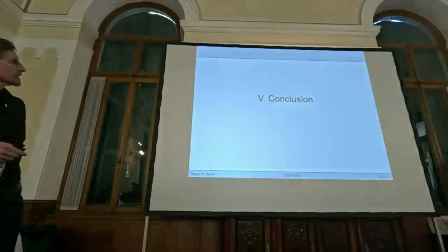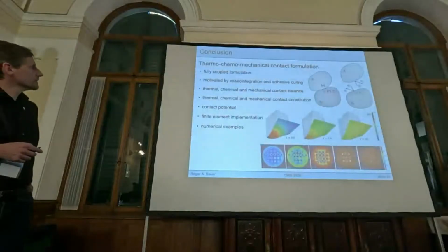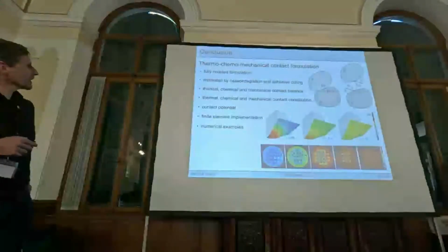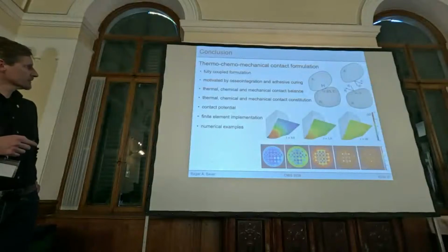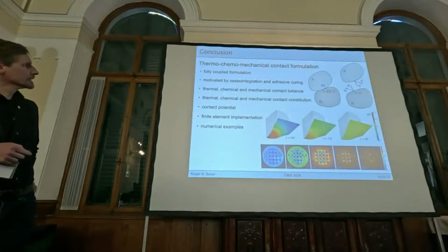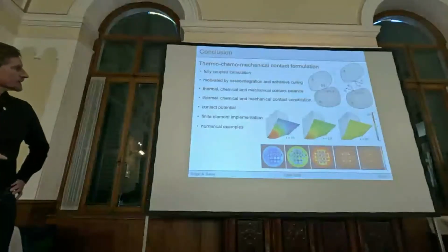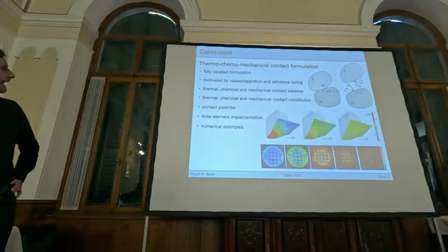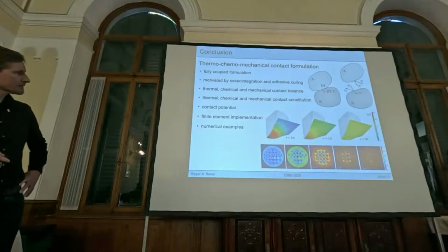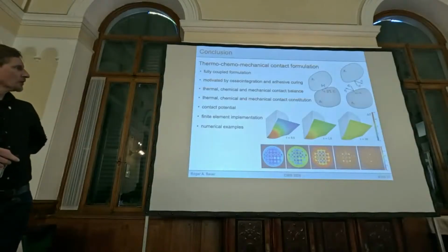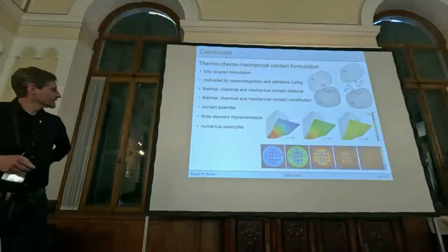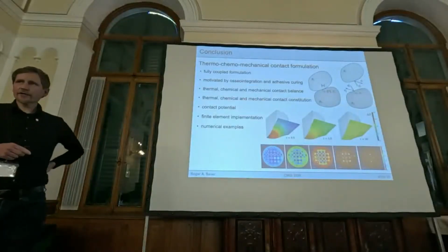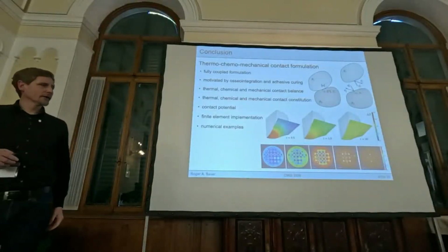Okay, very well. So let me conclude. It's a fully coupled thermal, chemical, and mechanical contact formulation. It's mostly motivated by natural bonding and also industrial bonding, for instance, adhesive bonding. And we have studied this first from a theoretical point, looking at the balance laws and the constitutive equations, and looked at the potential that would be suitable in this framework.